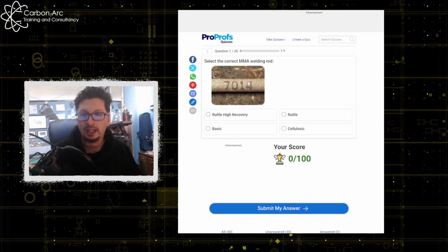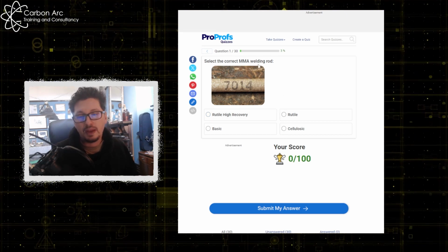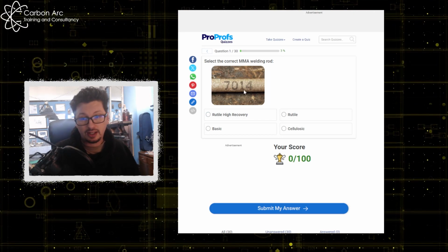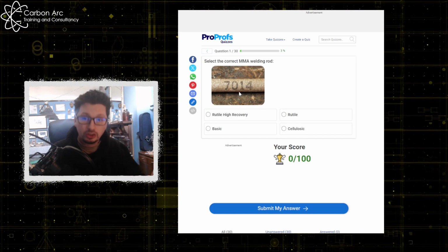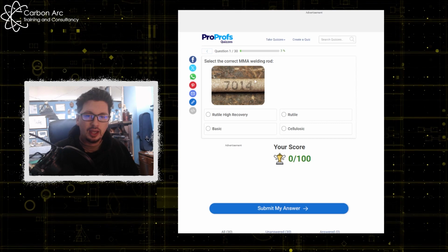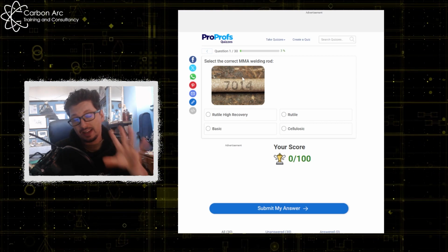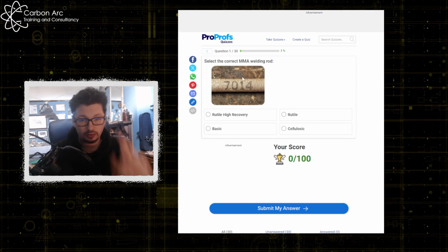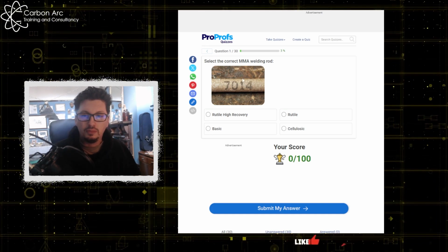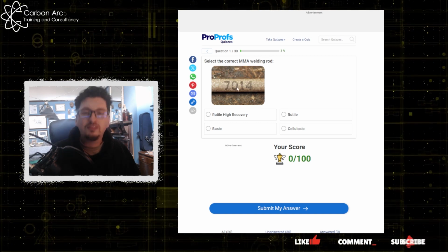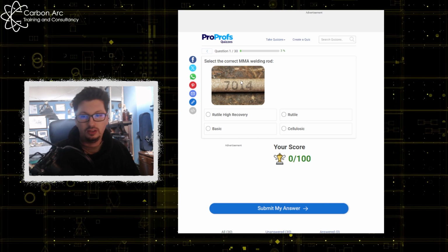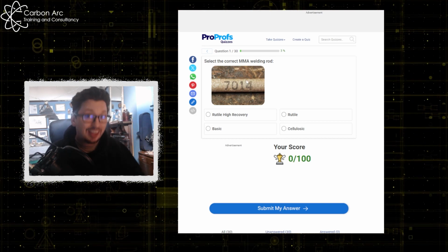So first one here, select the correct MMA welding rod. We're being given an AWS classification covered electrode. So we've got a 7014 electrode here. We do have a video on identification of electrodes on our channel, so make sure you have a check of that. But what we've got here is 70,000 PSI. It's all positional, and it's a rutile type electrode.